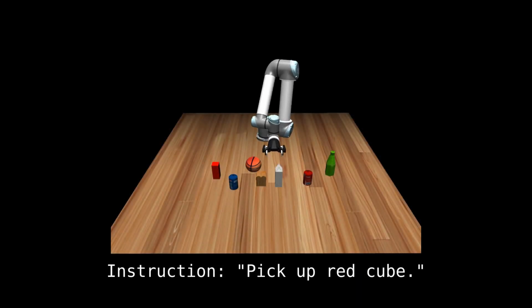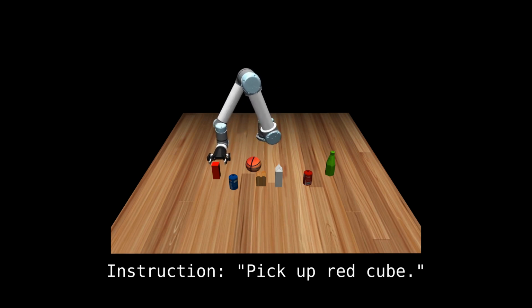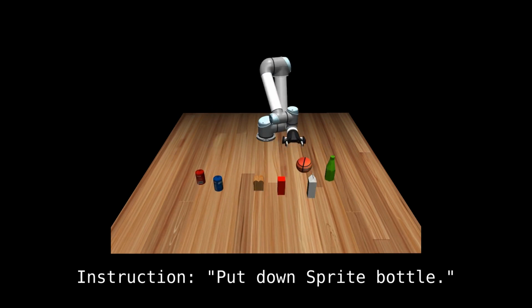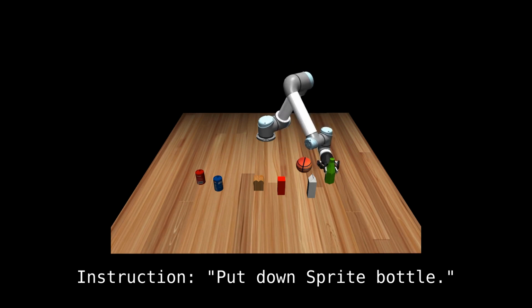We also test our model's ability to add new modules to the existing hierarchy by incorporating an obstacle avoidance behavior during manipulation. To this end, a new module is included for detecting an obstructing obstacle. Thereafter, the robot is able to calculate the displacement between the obstacle and the end effector, and thus avoid collision with the obstacle.